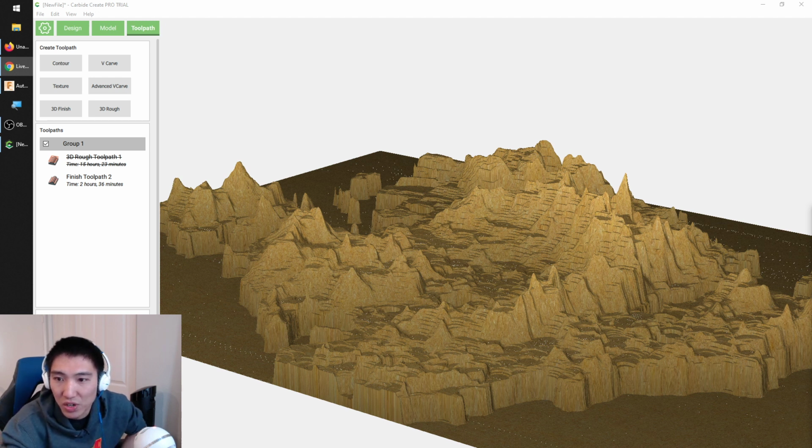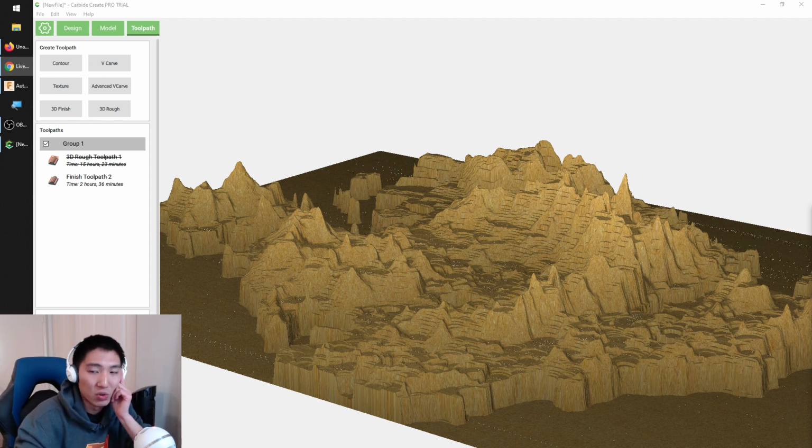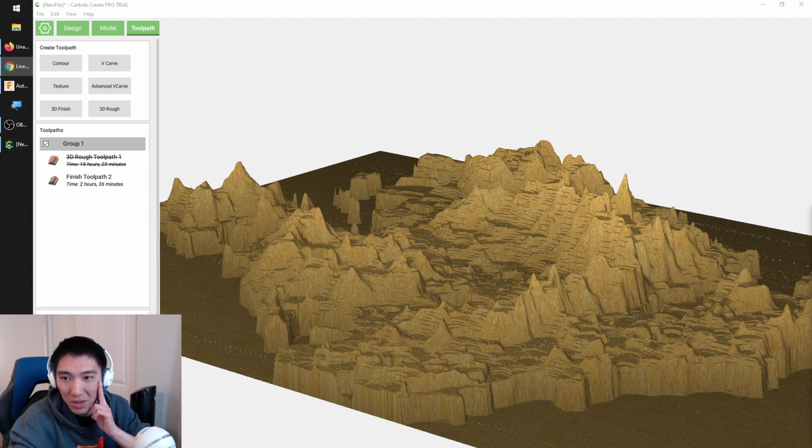Are you able to send signals to the Shapeoko mainboard for other accessories, like laser power relays? There's one digital output that you could tap into that would normally be reserved for coolant. I've seen one guy who made a relay board that could turn a fan or a vacuum on and off. So you could modify something like that, and you can DIY your own thing, or there's a chance we might be able to release something to allow you to do that in the future.